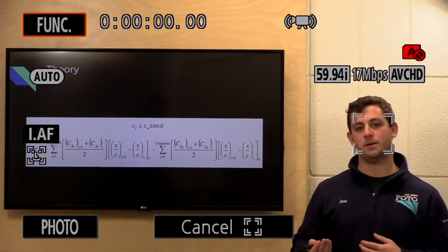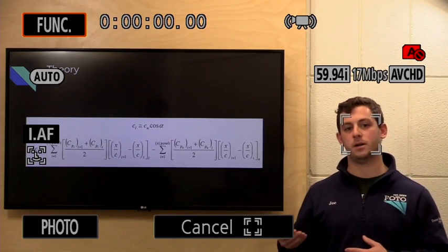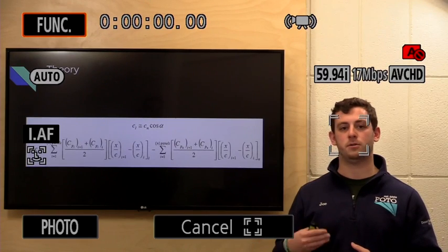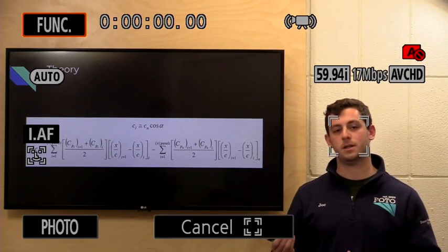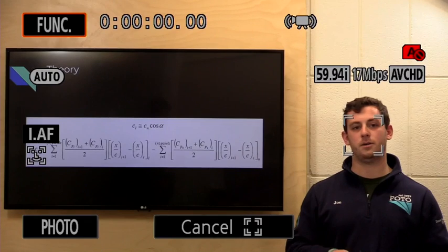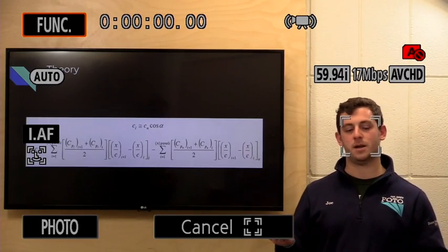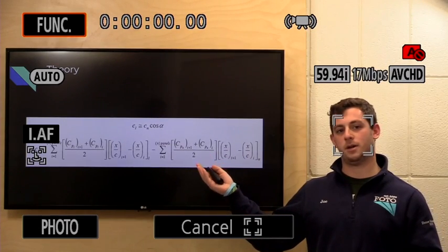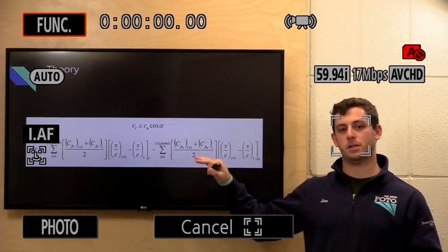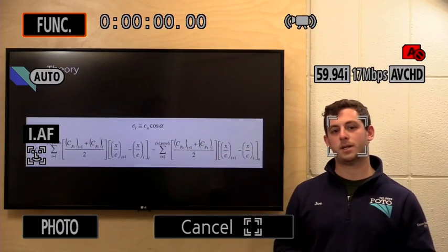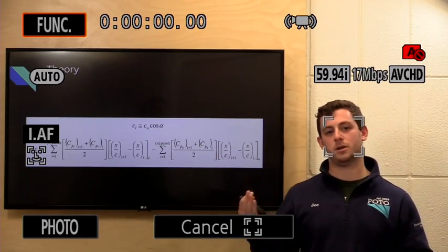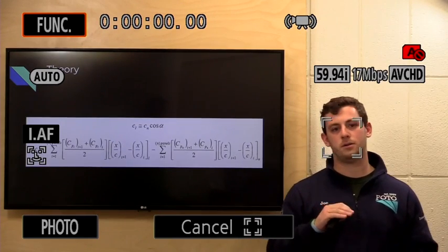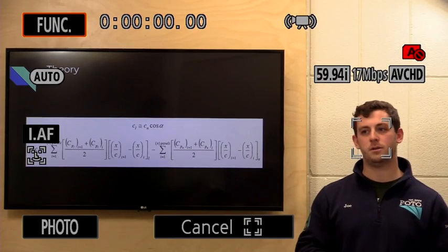So now that we have these individual components of our pressure coefficients, we can bring them in to find a coefficient for the normal force that actually generates lift. So this is done in a mesh numerical methods manner, where we actually have to look at the series and integrate over the entire surface of our airfoil, where we calculate for each pressure coefficient coming together to form the single normal coefficient on our airfoil.